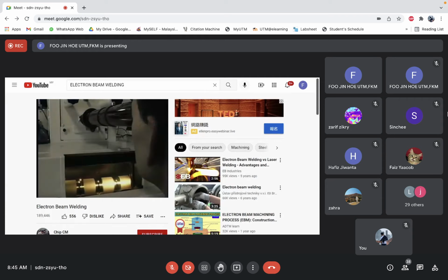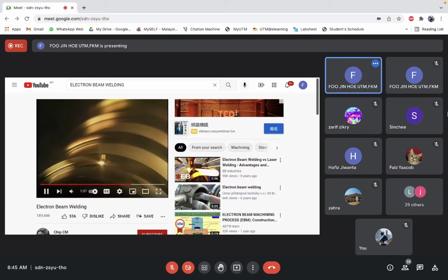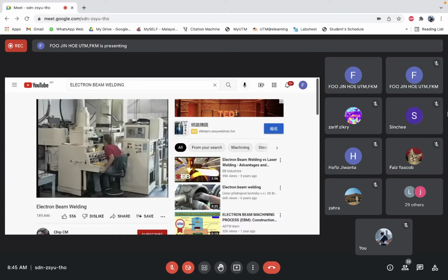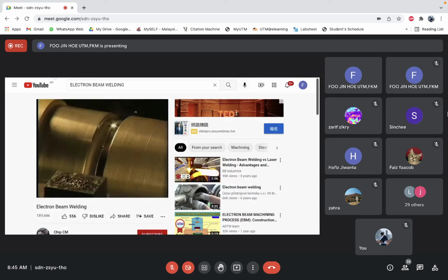Additionally, joints inaccessible by other welding processes can be welded. Virtually all ferrous and non-ferrous metals, thin or thick, can be joined. Welding speeds are fast, and filler metal is not generally required. Equipment cost for electron beam welding is typically high, and welding is generally limited to machined parts assembled in primarily butt, corner, and lap joints.